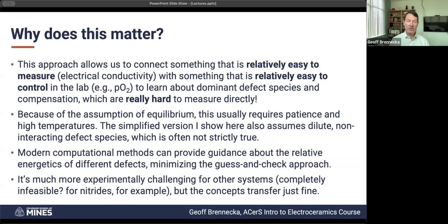It's usually easier to measure really tiny signals in AC than in DC, because in DC you're just looking for a trickle of electrons, and the noise associated with that DC measurement may be hard to avoid and hard to get a large enough signal over.